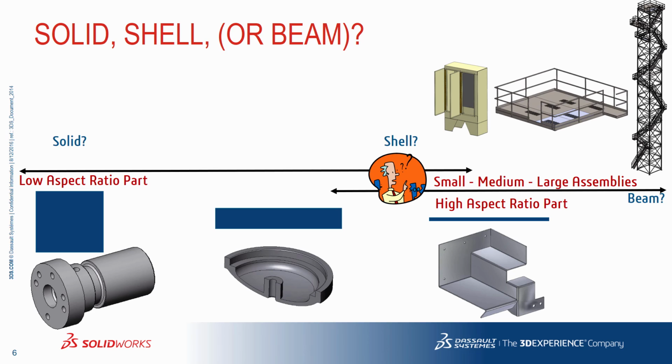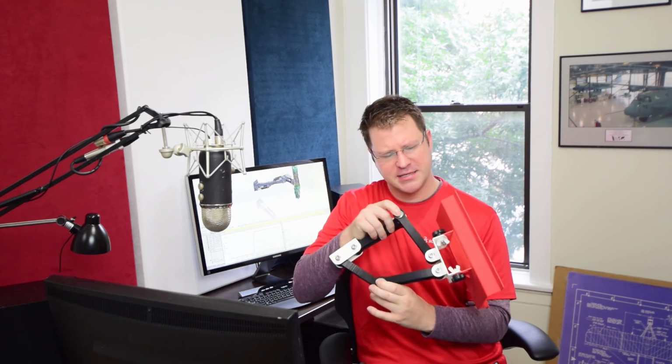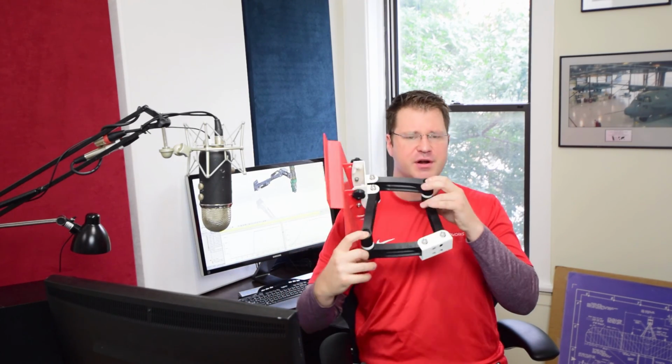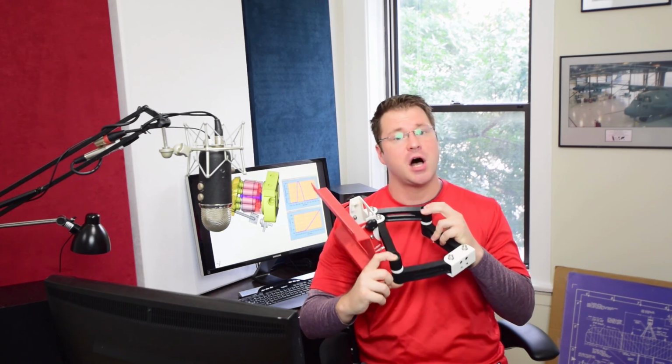It can be difficult. This little lid piece there, you could almost visualize that as a shell. And what I mean by that is if you can imagine representing this part, this solid part, as just a surface body in SOLIDWORKS and still have the same visual of the structure, it might be a good candidate. I mean, look at this example here. This is the monitor arm from concept before CAD. And think if we wanted to analyze this. Now, again, I could throw solid elements at this, but look how thin the sheet metal interface bracket is, if you can see that.